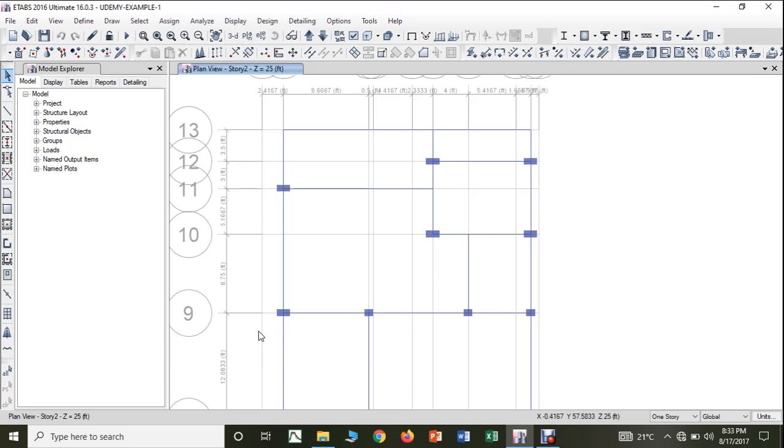If the column projections are outside the houses, no issues, but if they are inside, it is a very good orientation if they are covered along with the walls. Keeping these two concepts in mind, we have to arrange the orientations of the column.